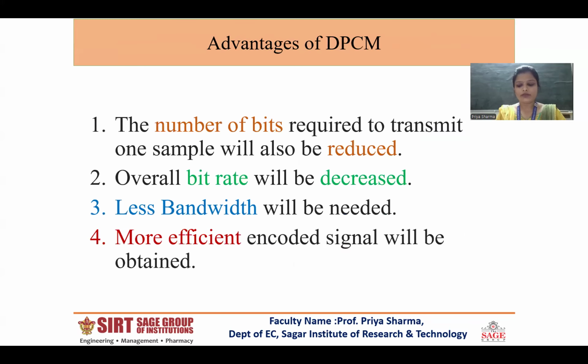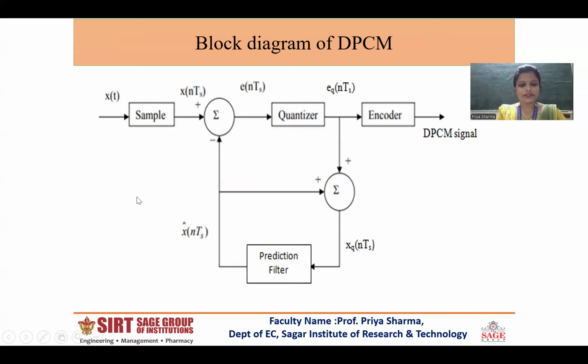Now coming to the encoding and decoding part of differential pulse code modulation. Basically, the analog input signal is band limited to one half of the sample rate. So sampling takes place here. It is then compared with the preceding accumulated signal level in the differentiator. Here it is compared. The feedback loop, or the accumulator, comprises a binary adder, a digital to analog converter, and an integrator.